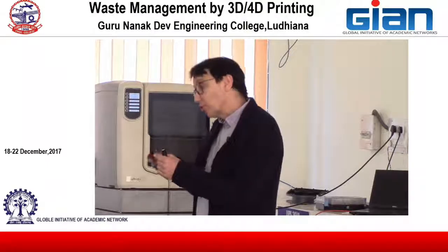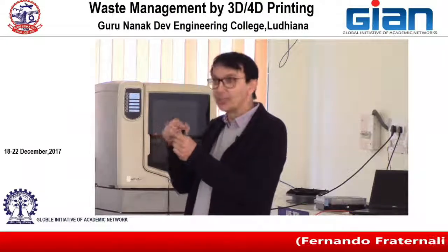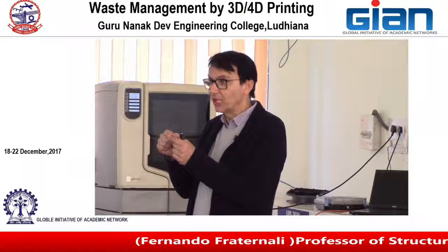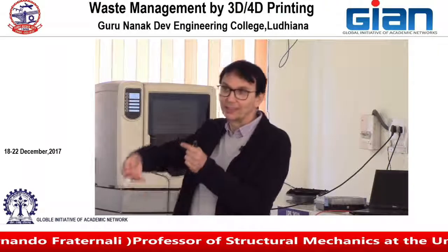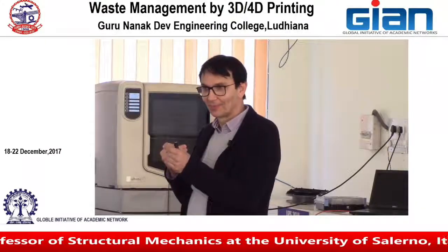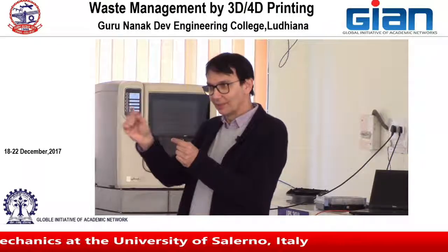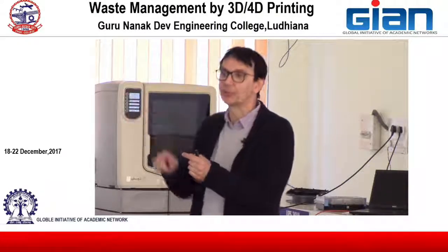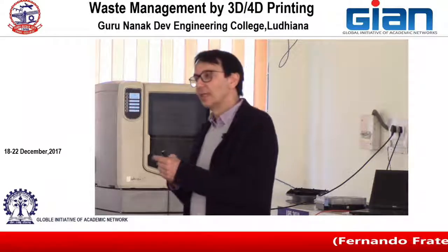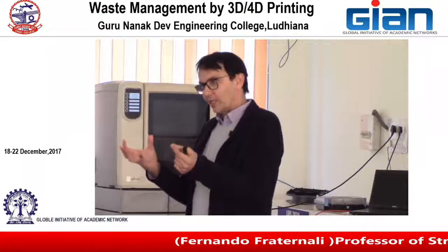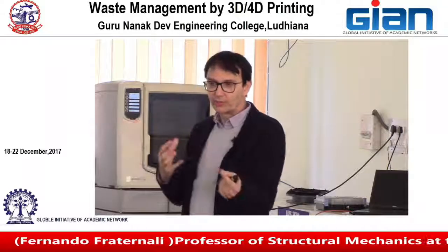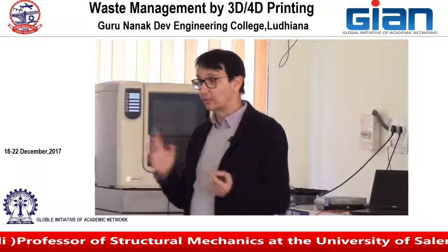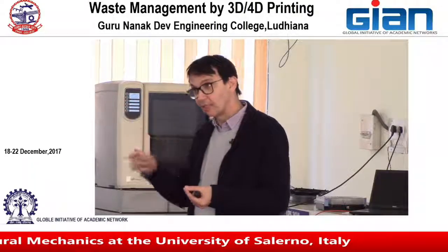Okay? Obviously, when you kill the elements in the epsilon neighborhood, you have to remove the elements that have already been killed before. So you take the killed elements, and you take all the elements that are in an epsilon neighborhood of that element. You obtain a volume or a surface, depending on whether you are in 3D or 2D, divide by 2 epsilon.